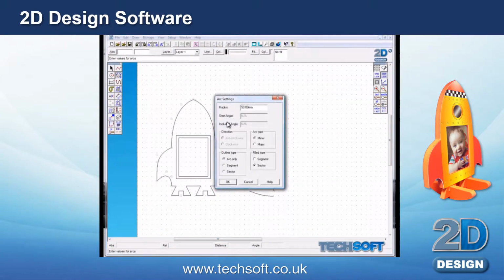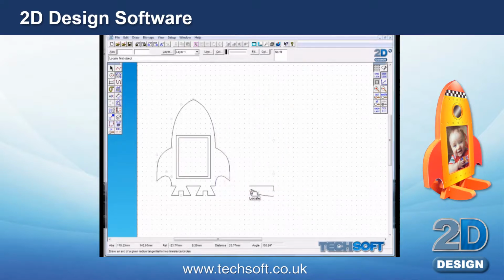Just another arc tool. What this does is just joins those two lines together. And do a radius of 3. OK that, and we'll select the top line and the bottom line, and you notice it's just join those together with an arc. Next we use the delete tool again, and just take away the bits we don't need.